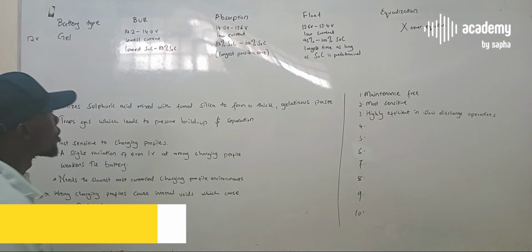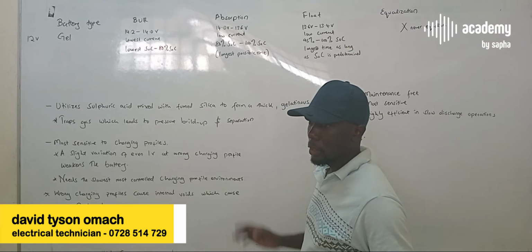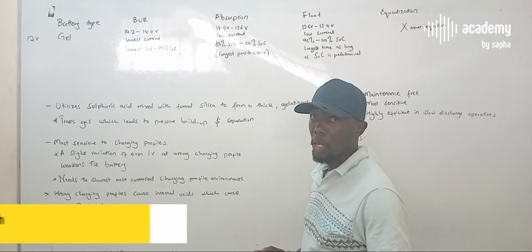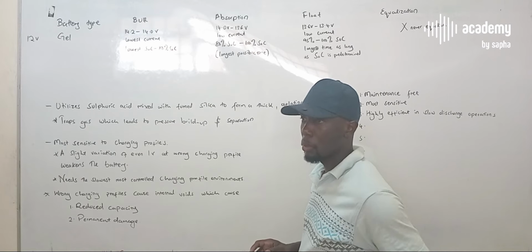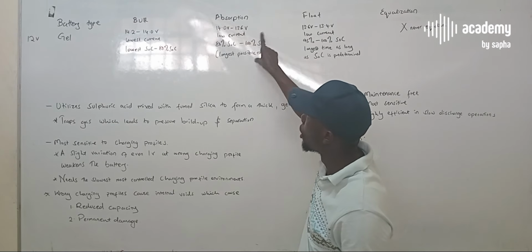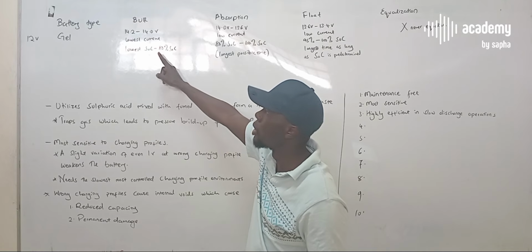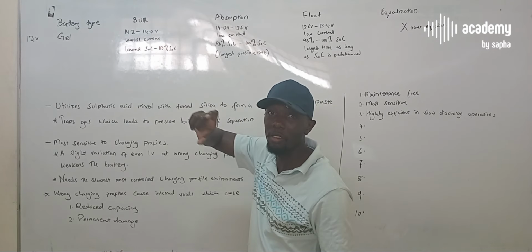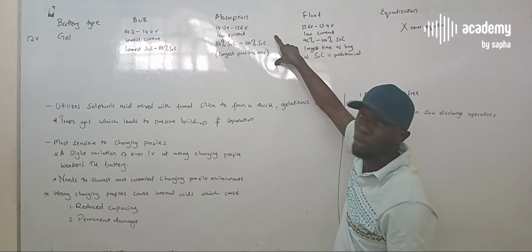It means that for the gel battery, the longest time a gel battery should spend during the recharging part of the cycle is at the absorption stage, because most of them will not be depleted below 60%. So from 60 to 80% will take a very short time, and you move it to the absorption stage.